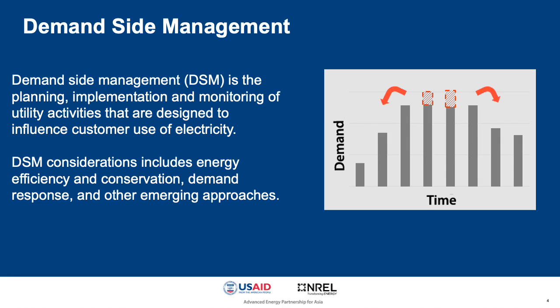DSM traditionally includes energy efficiency and conservation and demand response. But new additions to demand-side management include distributed energy resource management, such as smart electric vehicle charging, rooftop PV, and behind-the-meter storage devices.